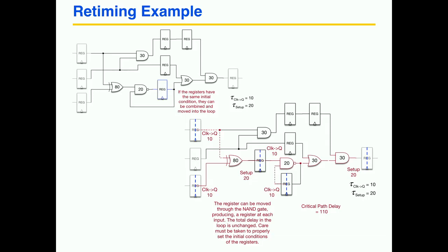Okay, so that's the retiming technique, and that's a very popular technique that designers use in order to do timing optimization. It's kind of related to pipelining, which we'll talk about later. And pipelining is the same idea, but you add registers where you didn't have them before. You don't just move them around, you add new registers into the circuit. What pipelining does is change the input to output relationship. It adds extra delay to get from input to output. But in the process of doing that, you can increase the clock frequency by having shorter stages of logic.